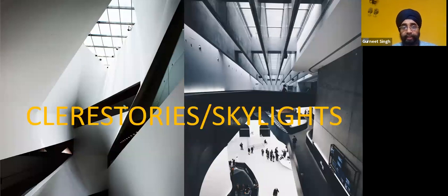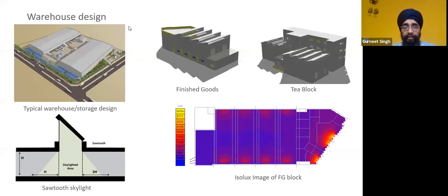Then clear story and skylights is another strategy. So generally, all the typical warehouse and storage are done like this. So they have shed-like structure with small skylights in between. This is what we did for Organic India warehouse, where we brought in clear story and the skylights. So this is not facing sawtooth skylight.